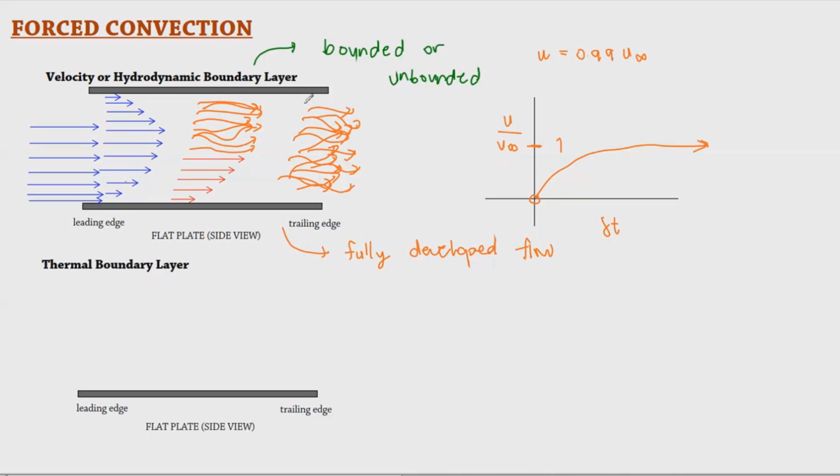And that's why it is logical to say that if the fluid is viscous, most of the time it will be laminar, since the viscous force will be a lot larger than the inertial forces. So this is just a short review of your Reynolds number. This is the laminar, wherein the layers of the fluid do not actually mix. And then there's this transition where it starts to mix, and then there's the final, the turbulent, in which the layers are just disturbed.